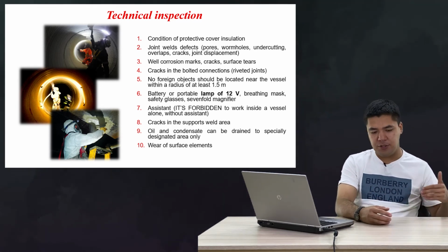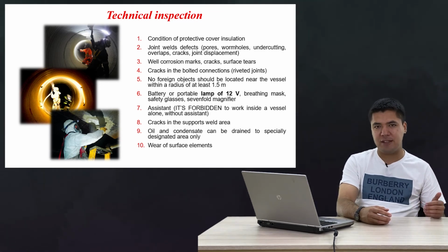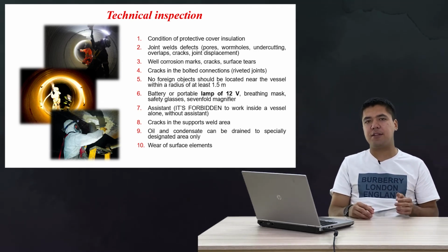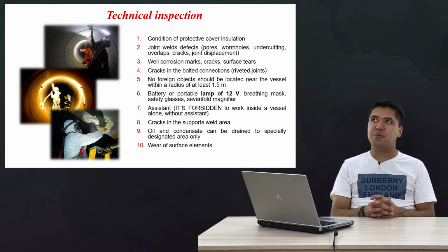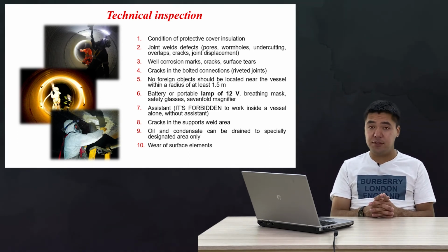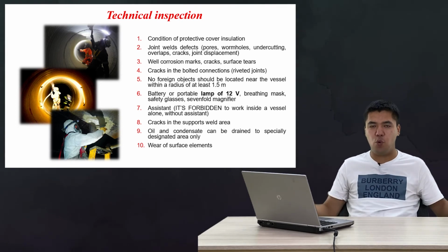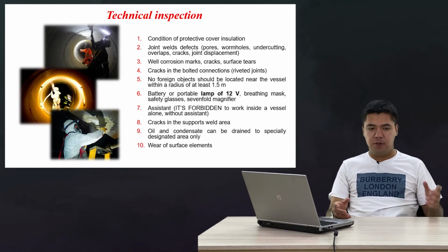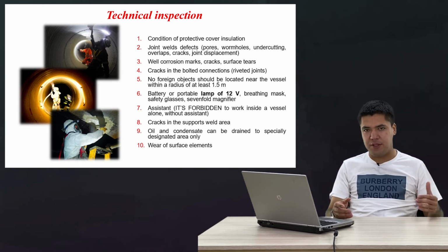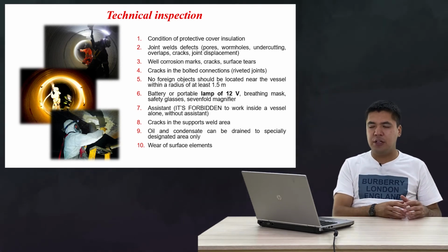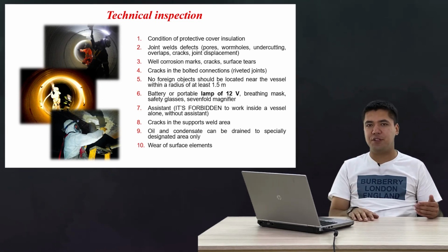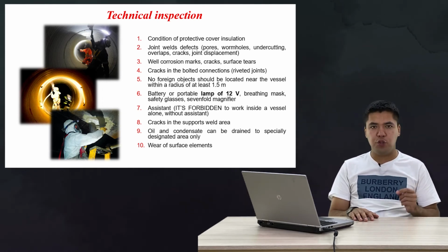And if you want to enter the pressure vessel, you need to know that a pressure vessel is a confined space. In our industry, in Kazakhstan, mostly in my experience I work with the oil and gas industry, and in the oil and gas industry vessels always used to contain byproducts of the oil. And imagine even a small amount of gas remaining in that vessel; in case of using non-intrinsically safe devices with very high voltage, it may lead to an explosion. That's why lighting must have no more than 12 volts.